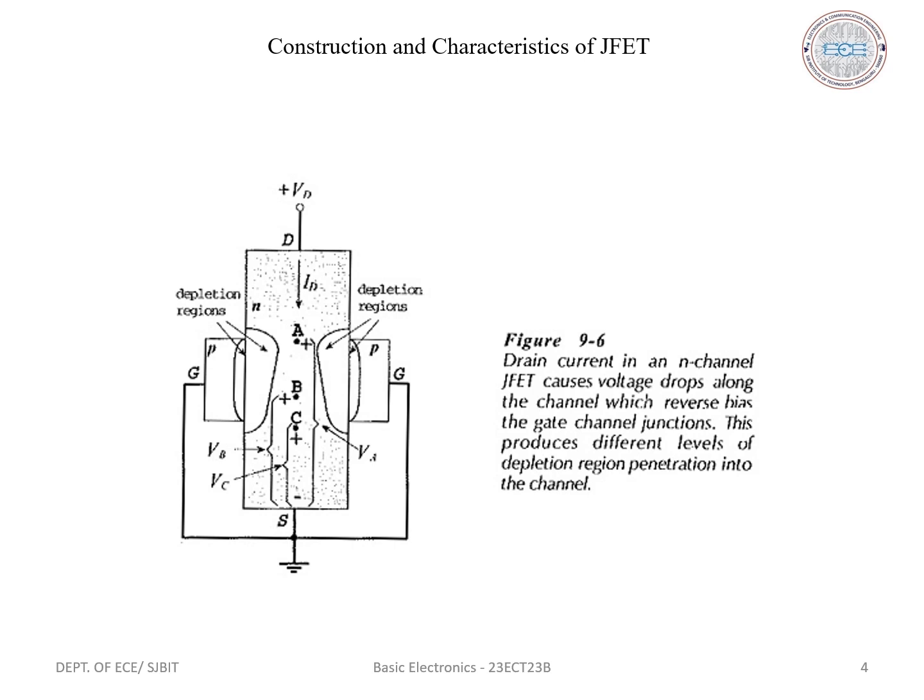ID becomes 0. When an AC signal is applied to the gate, it results in an increase in reverse VGS as the signal goes negative. This decreases when the signal is going positive. That is, when the reverse VGS increases, the width of the depletion region also increases. This in turn increases the channel resistance and the flow of drain current decreases. When the signal goes positive, the depletion region reduces, channel resistance also decreases and the drain current increases.